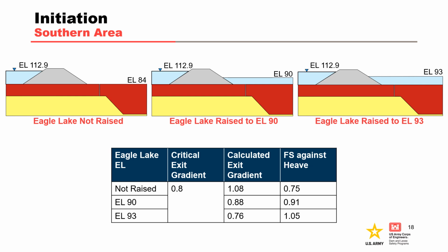However, the increased lake elevation successfully reduced the expected foundation seepage gradient to near the critical gradient, and it's likely that the probability of backward erosion piping initiation was decreased.